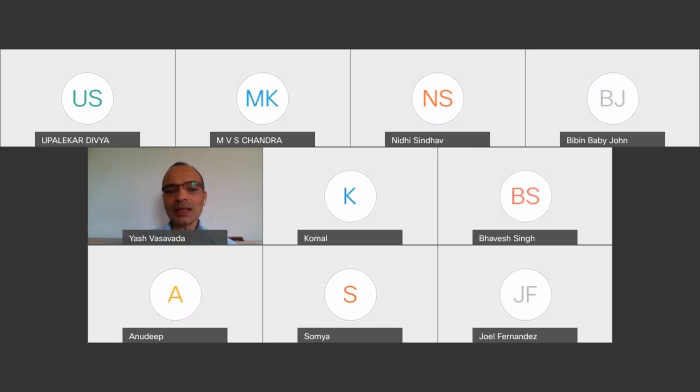And so that becomes the challenge. And the paper that we are now going to look at is focusing on the same challenge. In fact, a lot of these papers on massive MIMO beamforming or millimeter wave techniques are all trying to solve this challenge: how to maintain the performance advantage that you get if you have a large number of antenna elements, that capital N in our notation, like maybe 100 or 200 or 300, but still not incur a very large cost of implementing such an antenna array.